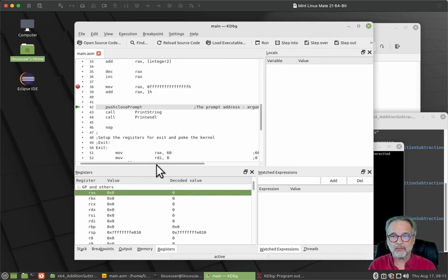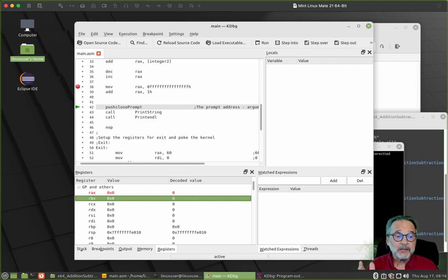It wrapped back around. It had the maximum value in there, and when you add 1, everything turns off, but we lost a bit. Something should have gone into the 65th bit, but the CPU isn't a 65-bit processor. So where did that lost bit, that overflowed, where did that go? Well, I'll tell you where it went. It went into the carry flag.